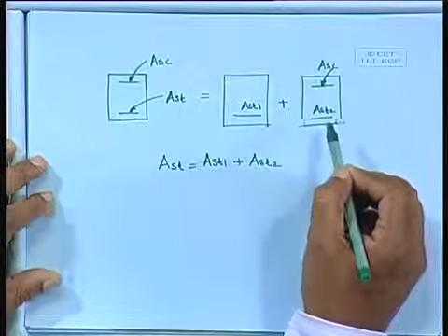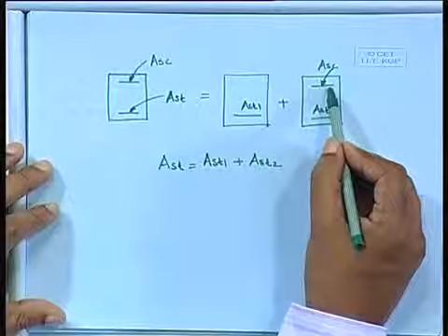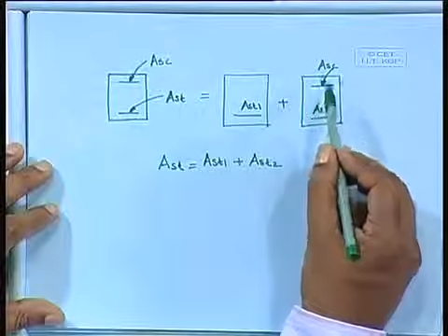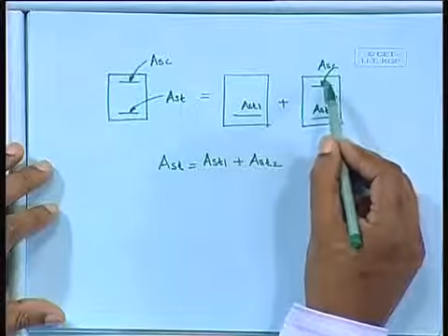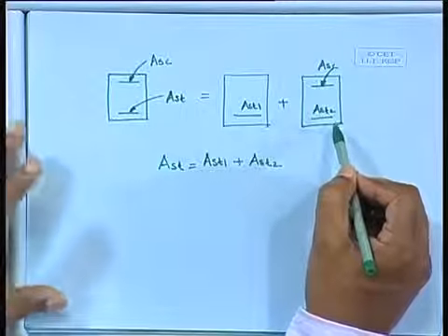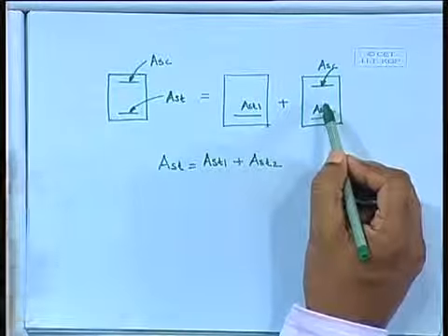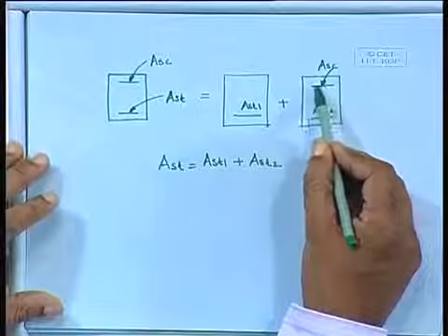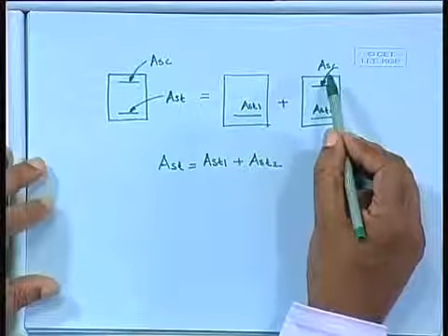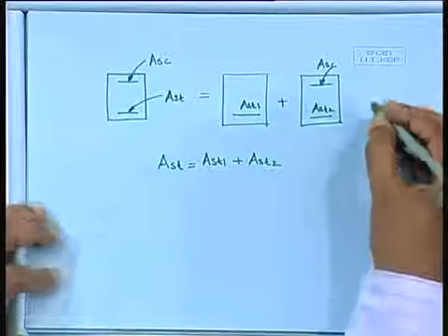ASC and AST2 cannot be equal, because the strain in the top portion and the strain in the bottom are different, or in other words the stresses are different on the two sides. The forces are equal, because they are in equilibrium, but the areas ASC and AST2 will not necessarily be equal, because stresses are different in different zones. I could further explain.